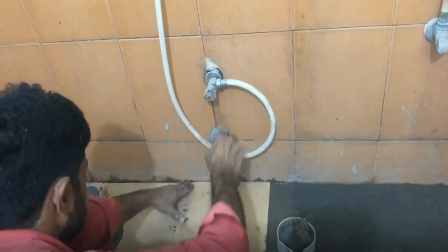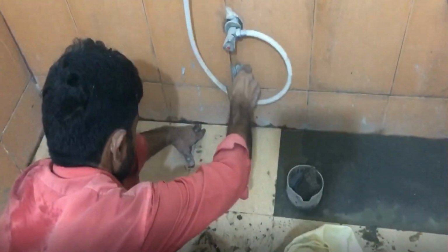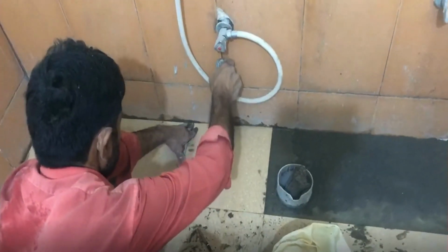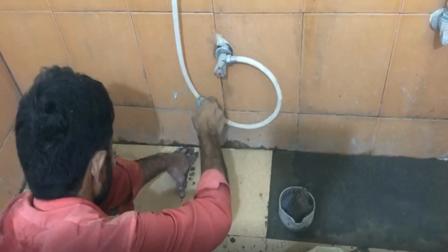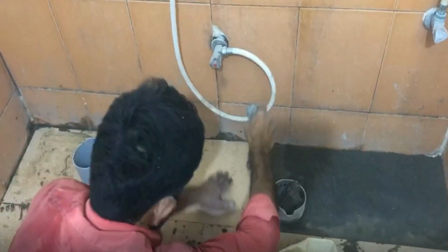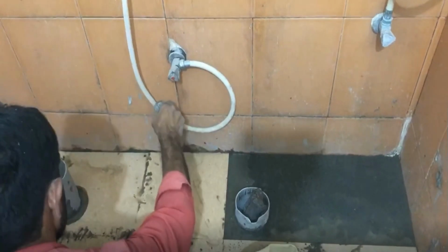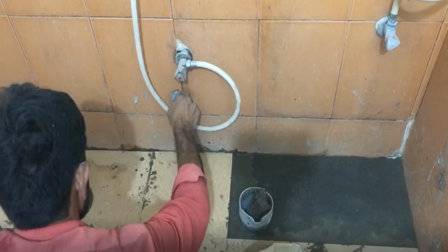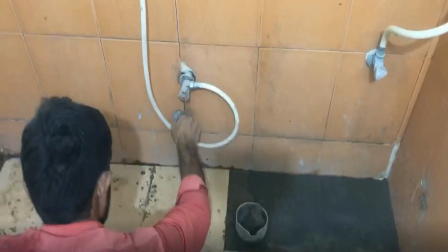In this video, let's discuss the cost estimation for bathroom tiles. How do we calculate the quantity required for one bathroom which is of size 6 by 8? How do we calculate the tiles quantity for floors as well as walls? And then how do we calculate the cement quantity and sand quantity? What is the cost of labor? What is the filler material we are going to use? So everything we'll discuss in detail. I'll show you with the proper calculations.